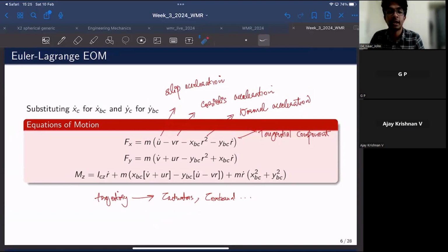Whereas if you derive an equation of motion using the Newton-Euler method, it is more comprehensive, such that you have to do this propagation from each and every joint, starting from the tip of the robot, the working tip or end effector, all the way to the base frame. So with that, you will also determine the reaction forces available at each and every joint. That could be essential if you're trying to design the links of the robot, so that you can estimate the maximum forces each of these links is subjected to.